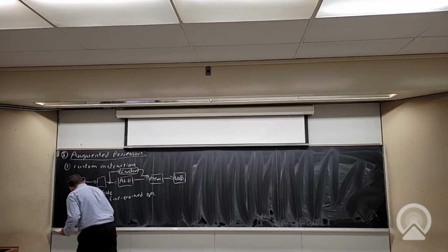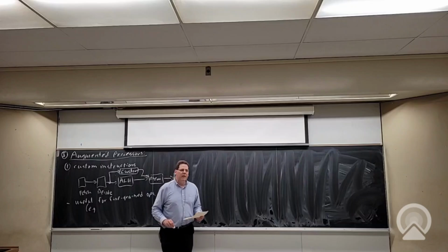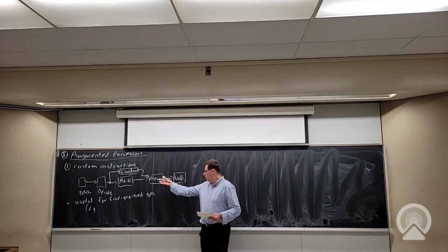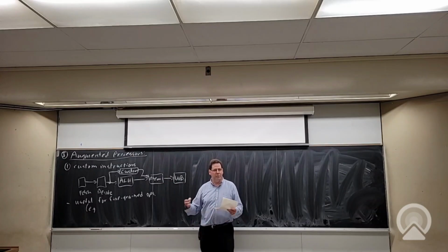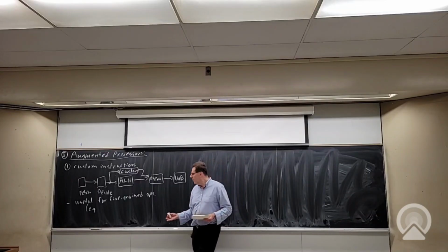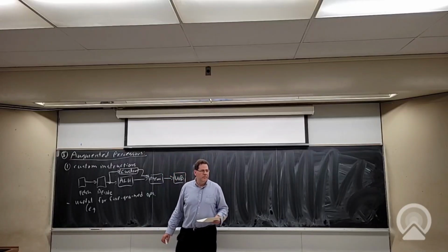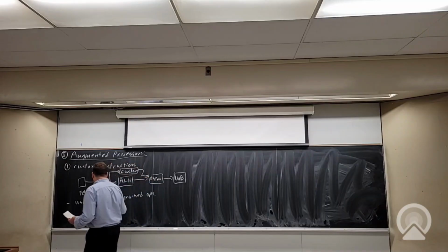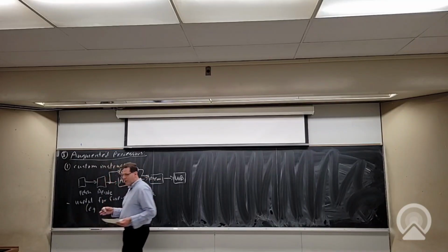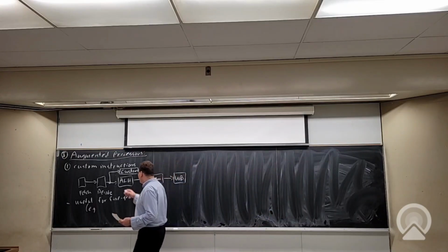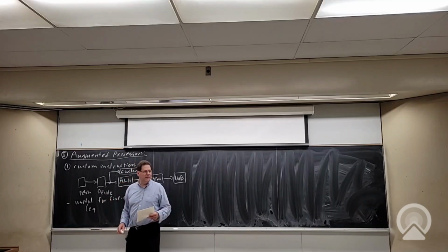I can give you an example where this has been used pretty successfully. Floating point is one example. Back before soft processors had floating point, but now often you can just ask for it, so we don't really think of it as a custom instruction much. But in that same vein, there's another set of instructions this has been pretty useful for. Yeah, what do you think? Multiply, accumulate. The thing is that's also gotten folded into the baseline ALU, where now you have multiply-accumulate operations. If you only had a multiply and an accumulate, then you could put a MAC in.